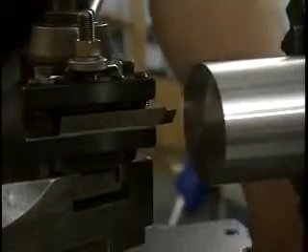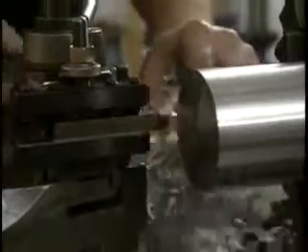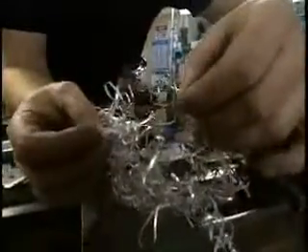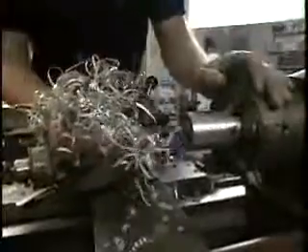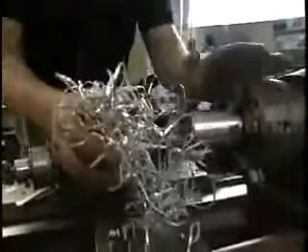Before removing the chips that you've just made from the machine, always stop the machine. These chips are essentially like little razor blades. In fact, Gillette makes razor blades in just this way. So with the machine off, then it's relatively safe to come in and remove the chips. However, if some of the chips are hung up on some part of the machine, and you pull too quickly, you're still likely to get hurt. So be very, very careful with chips like this.